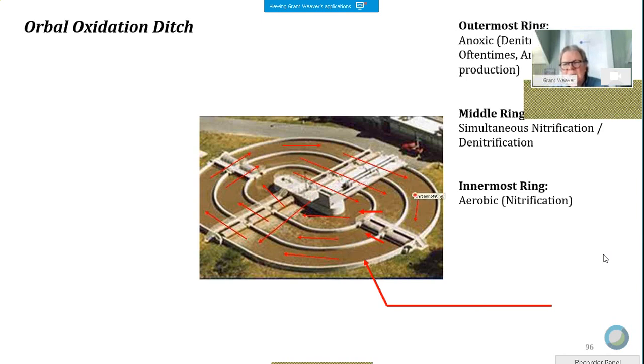And if there's no nitrates coming in here, by definition, this pump rate can be increased. If there are nitrates coming in here, then it's a dance. How much more you can bring into this zone without polluting it, and how little you can send in here without getting an elevated nitrate in your effluent. Because after all, it isn't how much coming through this wall that you want to maximize, it's how much going to the final clarifier that you want to maximize.